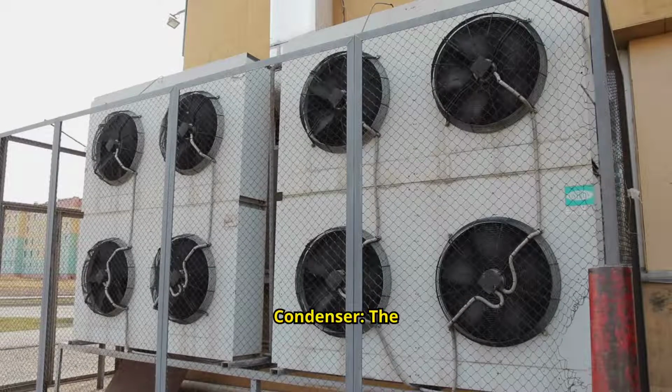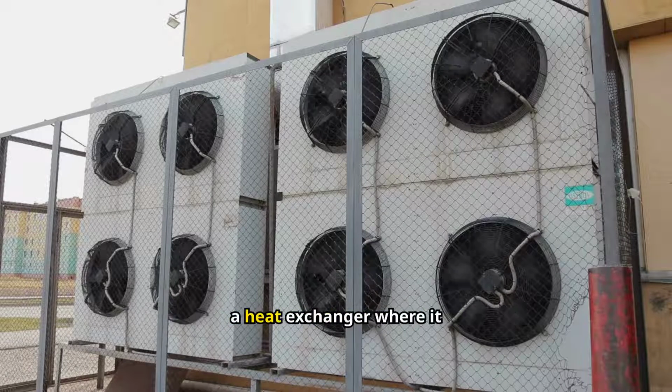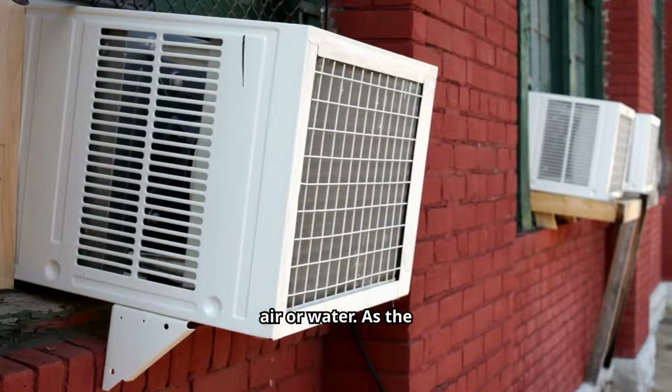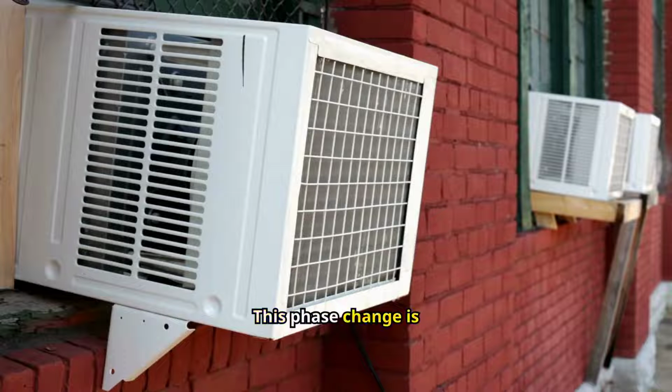2. Condenser. The high-pressure, high-temperature gas flows into the condenser, a heat exchanger where it releases its heat to the surrounding air or water. As the refrigerant cools, it condenses into a high-pressure liquid. This phase change is crucial, as it allows the system to expel unwanted heat.